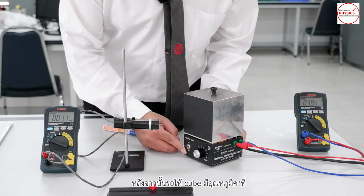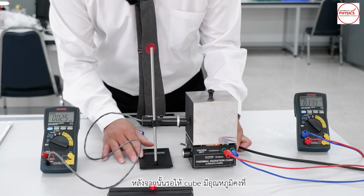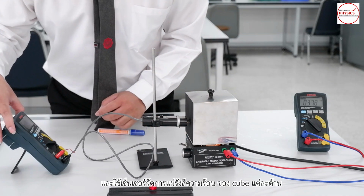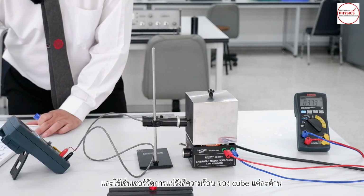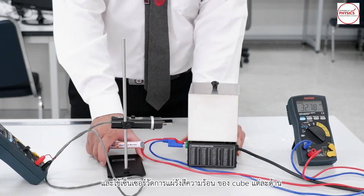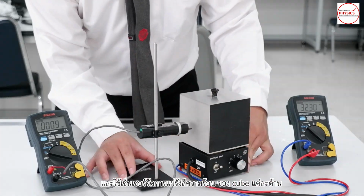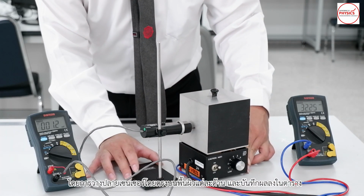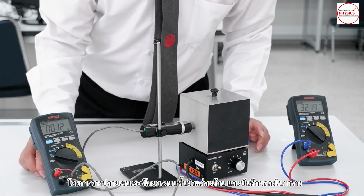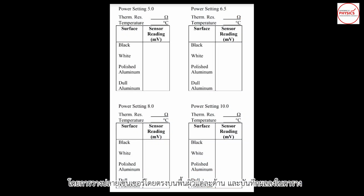After that, wait for the cube to reach a stable temperature, or thermal equilibrium, then use the radiation sensor to measure the radiation from around the 4 surfaces of the cube by pressing the sensor tip directly on each surface. Be sure to record the reading in a table.